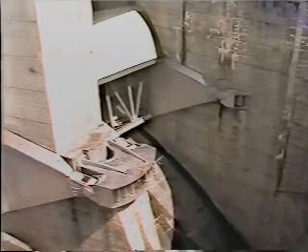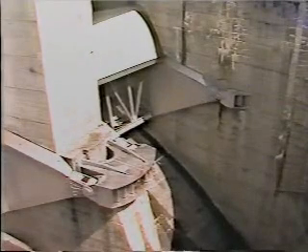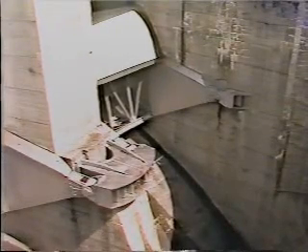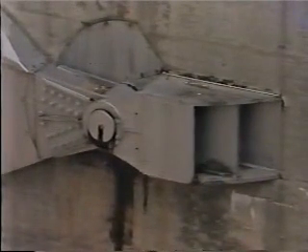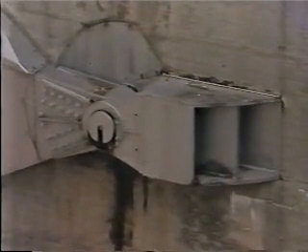Now you're ready to do a visual inspection of the gate itself. Be sure to check the pivot called a trunnion for signs of rust, wear, and inadequate lubrication. If possible, check the area of the anchorage for damage. If any part of the trunnion is badly worn, such as this pin, it must be replaced.